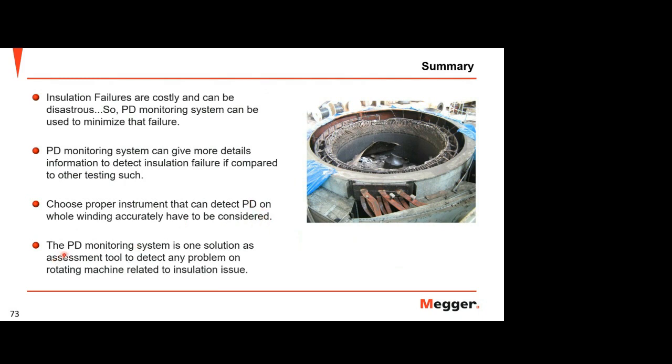And also the last one is that the PD monitoring system is one solution as an assessment tool to detect any problem on the rotating machine related to insulation issues without needing to energize your system. So you can detect early any failure indication. Yeah, I think that's all.